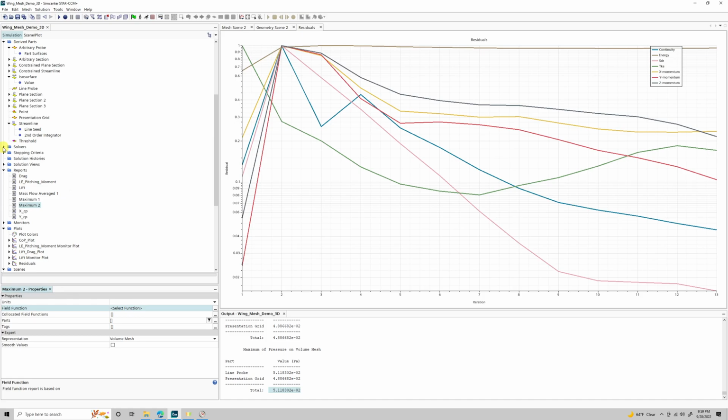It knows how much is left over in every cell after it stops its calculation, and it can add that up and normalize it. By normalize, I mean it takes the value for the first couple of iterations, treats that as a value of 1, and then if it goes down, it's a value of less than 1 for the future iterations. If it goes up, it's a value of greater than 1.